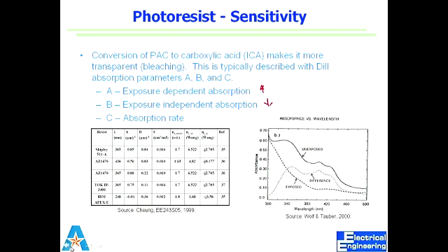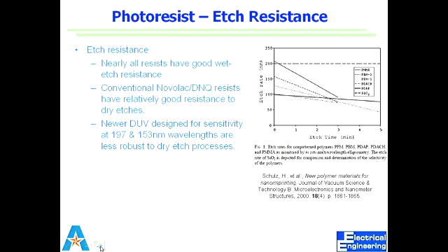So I know at one time we had a very deep trench, but the size didn't matter for us, so we used a resist which would give us 5 micron thick resist, very, very thick for that class of resist. But that gave us a good step coverage. I might have a picture of that as well. Okay, then we have to do etching.